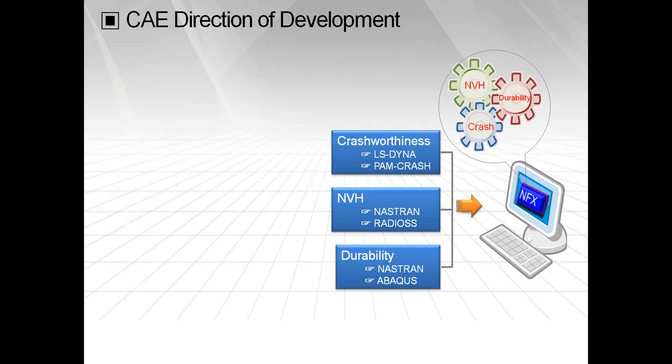And what I will tell you at the end is that usually in the car industry a lot of different solvers are used. So for crashworthiness, for example, explicit analysis with LS-Dyna or PAM-Crash is used. For NVH analysis, Nastran or Radioss. And for durability, again, Nastran or Abaqus are used. So the advantage of NFX is that you can do all this analysis in only one package.